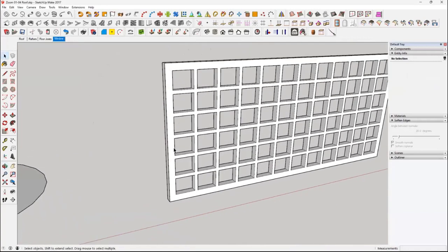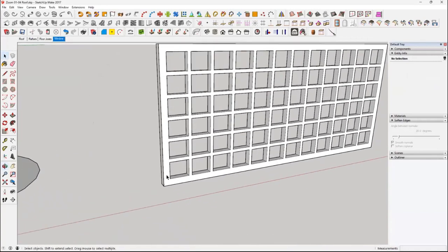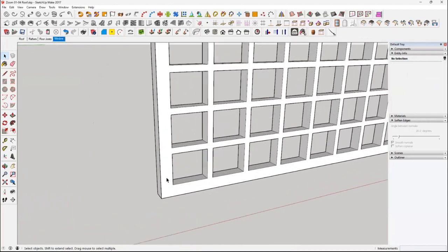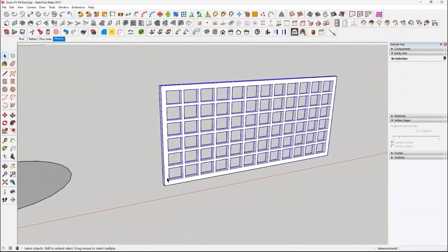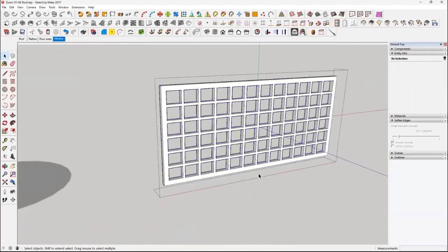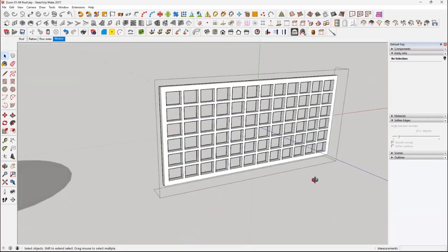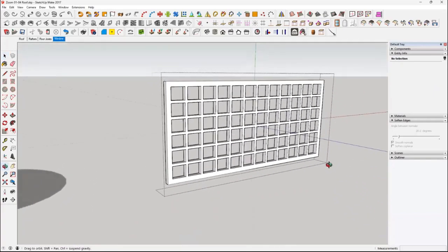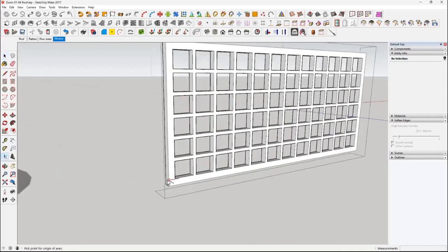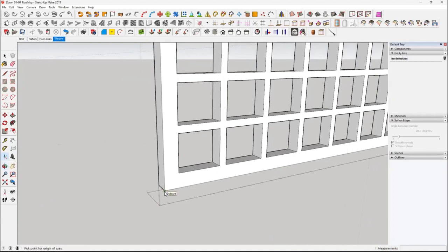So first thing we want to do is make sure our axis, this is an important one, is right. So if we click on this, double click, I don't know if you can see, but the blue axis is running from front to back. That's no good. We want the blue axis up, we want it how the model is. So what we need to do is, on the left-hand side, we'll come down and there's the axis button. If you click on it, and then we'll go to the corner, and we'll click on the corner.